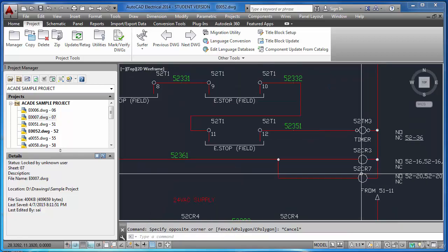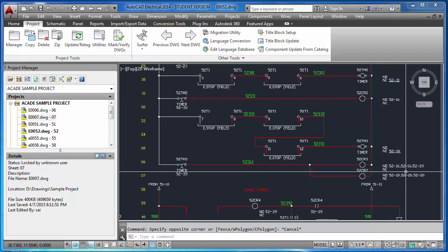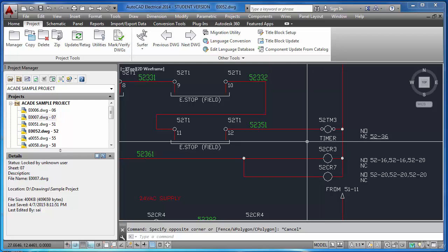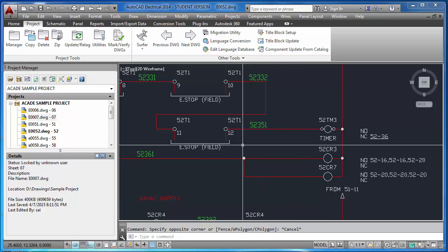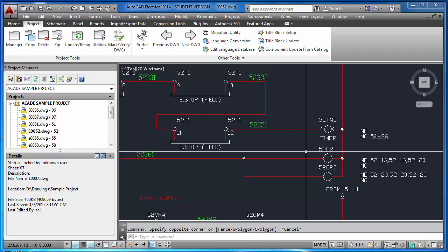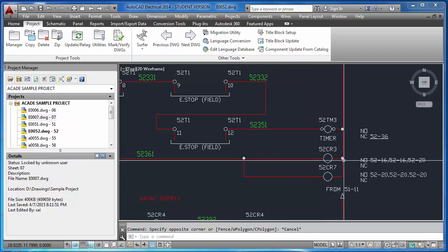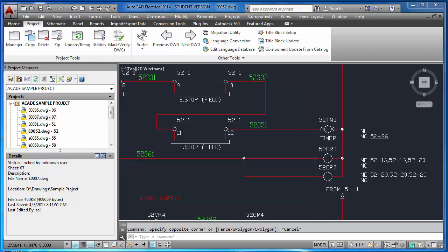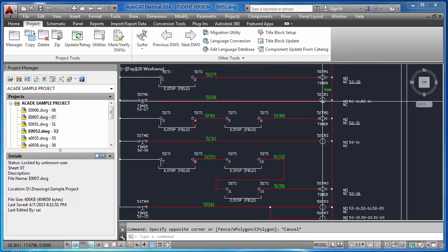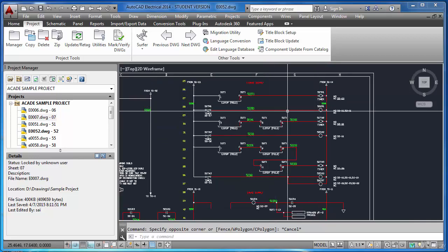You can see 2 relays because basically I initially considered only 1 relay. That relay was with 4 NO contacts, but while making the schematic diagram I came to know that I need more contacts, and unfortunately I had ordered 1 relay with 4 NO contacts. In that case, what I have done is I have inserted 1 more relay in parallel with this particular relay. So basically my control is 3 relays in this top circuit.